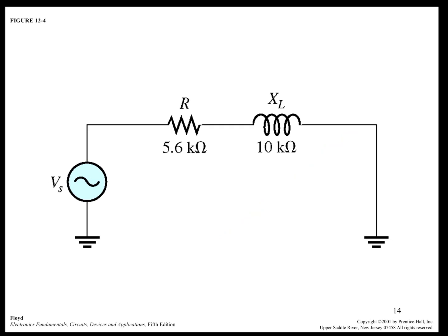Okay, so let's just take a simple example here. Here's where we have a series connection of R and XL. Notice how in this case you didn't have to calculate XL, it was given to you. So another example of this problem could be where you've been given a value of L for this coil and a frequency from the source, and you have to calculate it yourself. Remember, if you're not given a frequency for a source, you're to assume 60 hertz. And if you're not told otherwise, you're to assume RMS for your voltages and your currents.